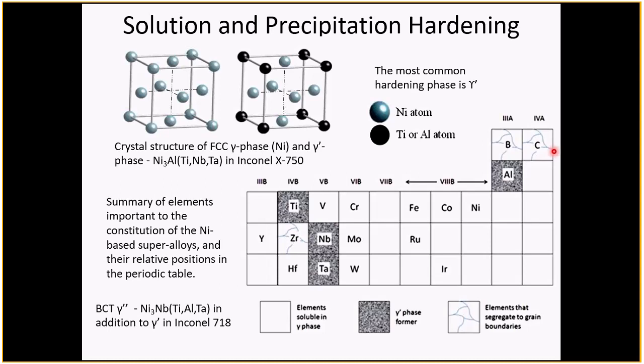There'd be preferential corrosion along the grain boundaries now because you have this depleted layer of chromium, and that's what's called sensitization. You may have heard of that in your travels, that you can heat treat some nickel alloys containing chrome, and the subsequent segregation of chromium carbides at boundaries depletes the chrome in the vicinity of the boundaries.